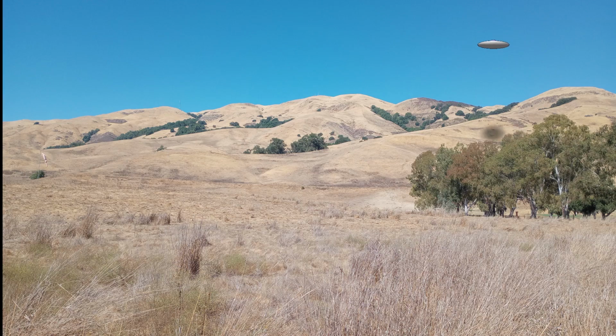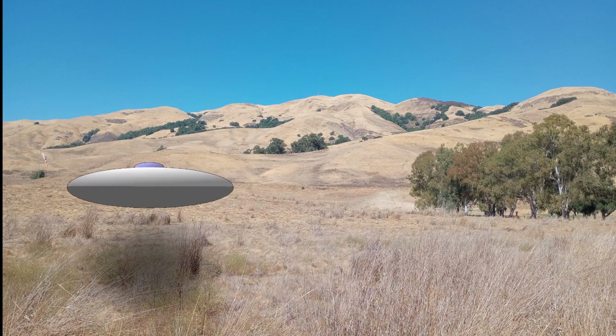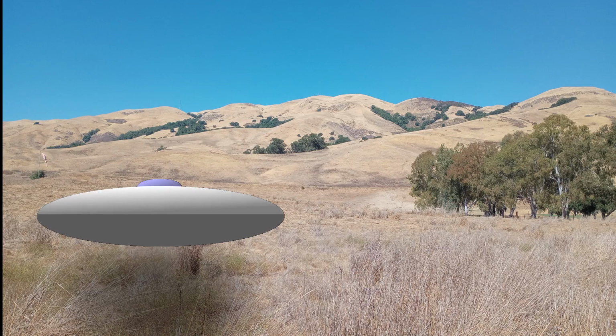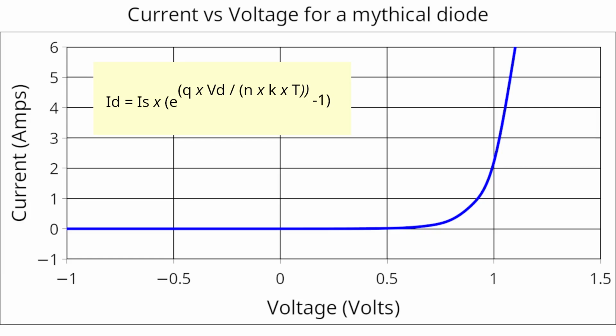At this point we need to go on a little bit of a side quest, because I realize that I'm about to use a number and some folks may ask what UFO I flew that number in on. We have all seen graphs of current versus voltage for diodes that look like this, with this equation. I draw your attention to the fact that the larger the current that is already flowing, the greater the change in current that will be caused by a small change in voltage.